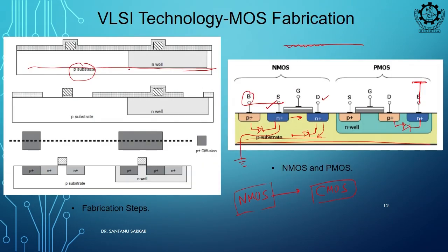You see that this is a P substrate. So, this is a P plus doping, and on this P plus doping some metal connection is there, that is it. So, what is a P tap? P tap is nothing but a P plus, and on this P plus some metal deposition. So, if you have a mask like that, this is P plus, and on top of this P plus you have say metal 1.